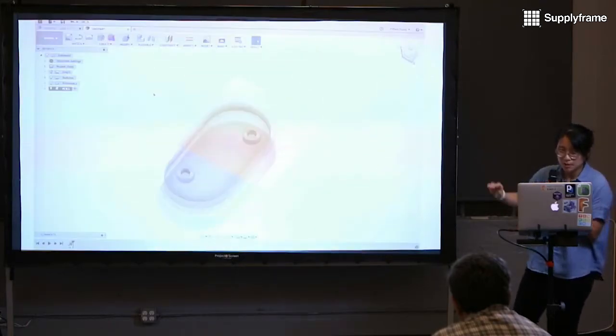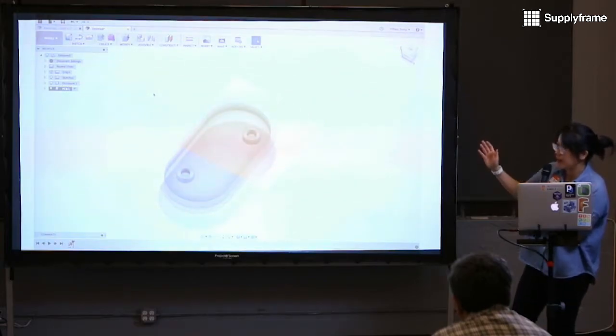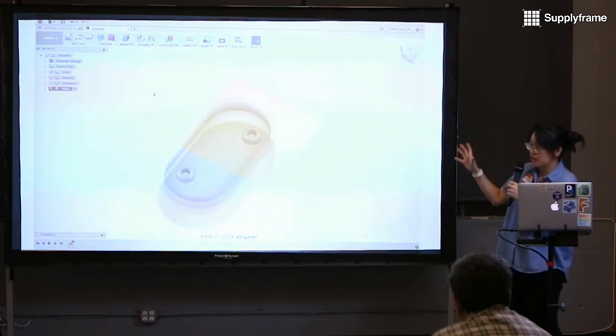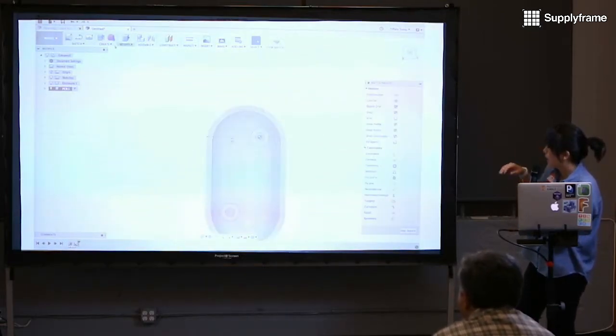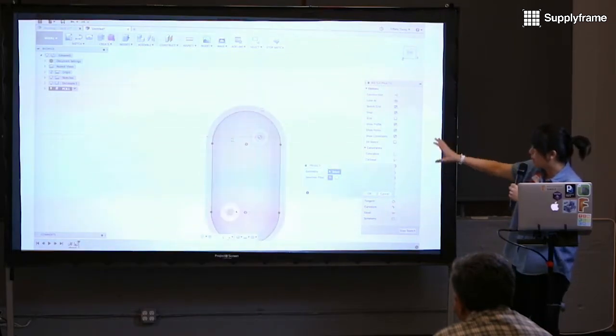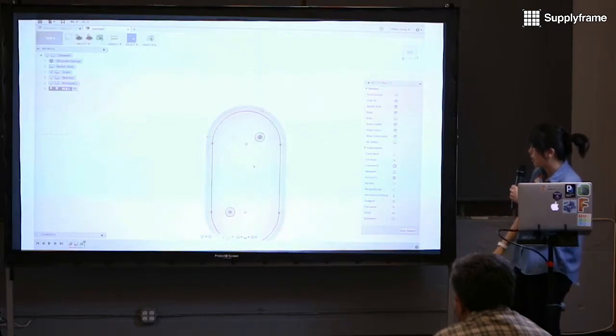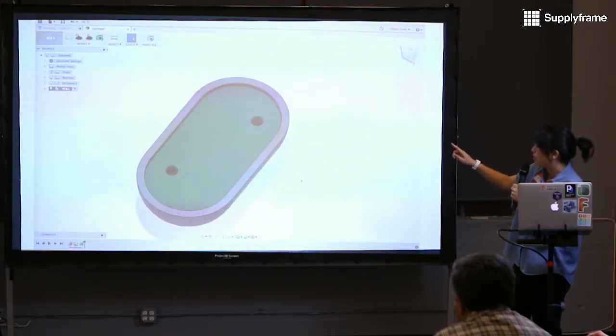So I'll show you what this looks like in Fusion now. In the first case, we're designing an enclosure around a custom PCB. So you actually start from Fusion, and I've already designed some enclosure, and then I can define my board outline, taking into account any standoffs or anything that I need to incorporate, and then I create a PCB feature.